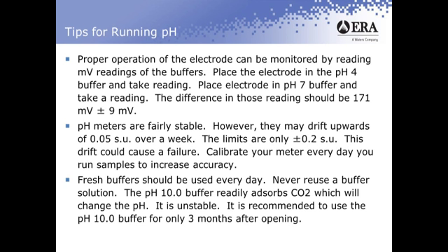Another thing that isn't widely known is that the pH 10 buffer will readily absorb CO2, which will change the pH. The pH 10 buffer is the most unstable of your 3 buffer solutions. In my experience, once you open the pH 10 buffer, only use it for 3 months after opening.